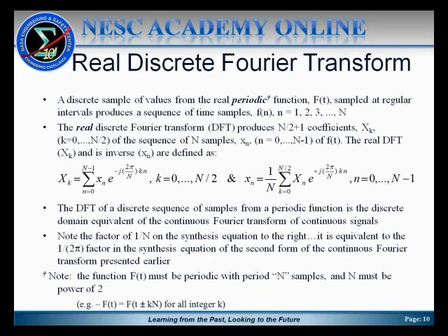Well, you can just make the assumption that they are if you have a collection of N samples of some waveform. That can be thought of, if the samples are large enough, as just a periodic sequence that will repeat that pattern. And so you still can analyze the content of the signal without knowing for sure that it's truly a periodic signal, such as a collection of sine or cosine waves.